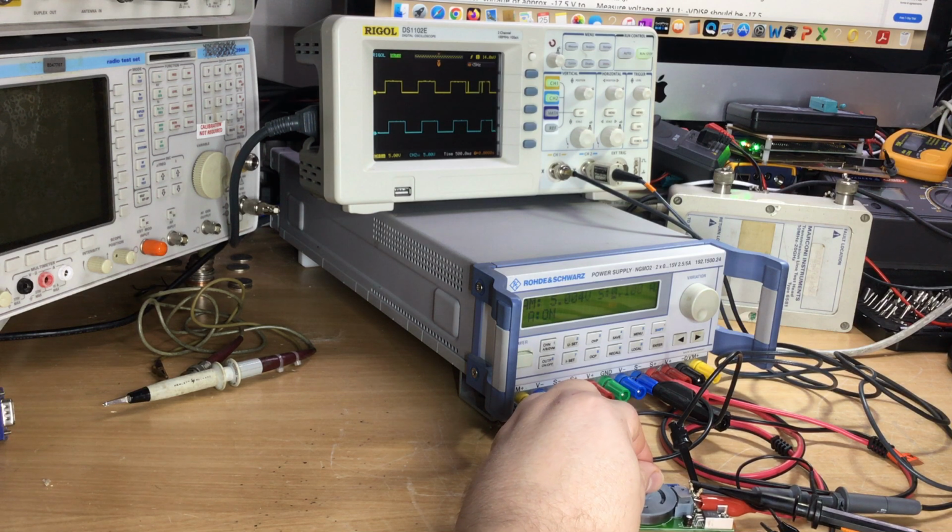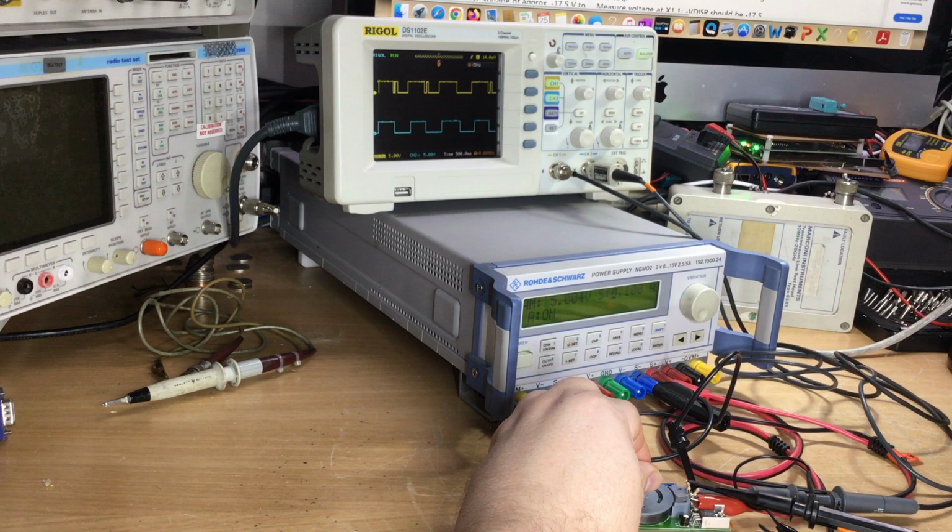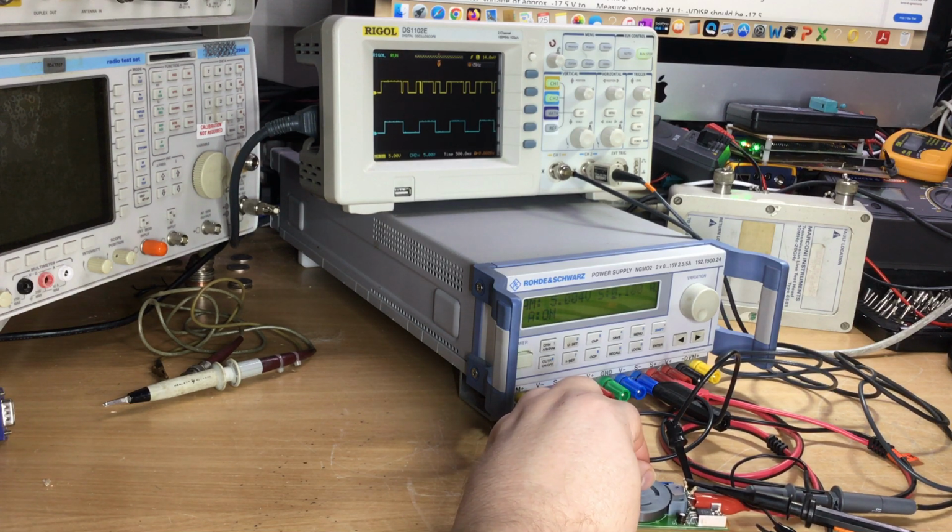So I think it's as those filings are going round on the wheel, or it could be the proximity of the Hall effect sensor as well. But I think the first thing to do is remove the magnetic wheel from the PCB, clean the magnetic wheel up, get those iron filings and contamination off it, clean up the Hall effect devices using isopropyl alcohol, and then reassemble everything, and let's try it again, see whether that sorts it out. If not, then it'll be looking at getting some new Hall effect devices to replace them with.